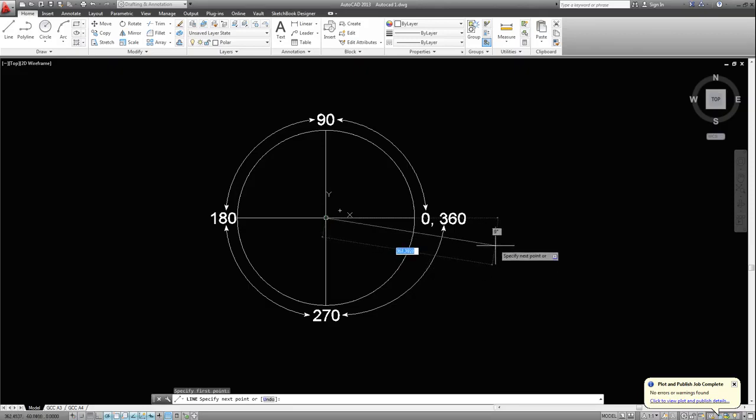The way we give AutoCAD its dimensions, you can see how it's highlighted, that will be the length of the line. The way that you get it in AutoCAD, now you need to understand this and remember this, maybe you write it down because it's something you always need. You press the shift key and at, and so that now you can see how it's set on the screen. You can see the at command. I'm going to make that line 300.